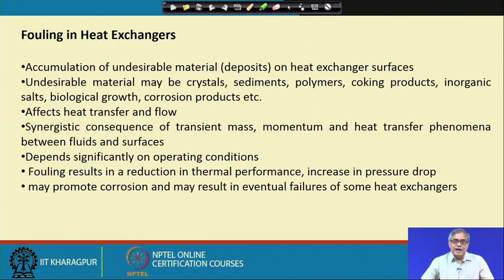Now, a new heat exchanger, when I am putting it in the system or in the plant, has no fouling. So, one might have designed the heat exchanger based on the assumption that all the surfaces are clean, the passage areas are known from the initial geometry of the heat exchanger, and some sort of performance prediction could be made. Already we have seen how to do it.